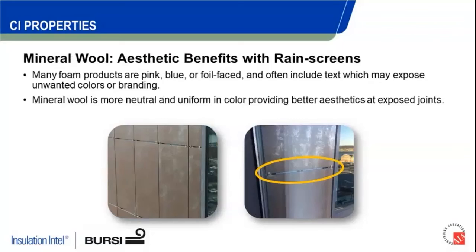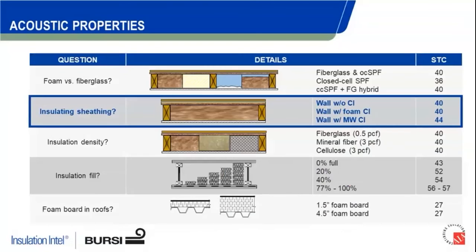Kind of almost get it in a darker, really base uniform type color that's not going to kind of telegraph through a wall system such as this. So just things to be aware of from an aesthetic standpoint. Cladding, fire performance aside, you do get a little bit better aesthetic benefit from that material if it's some type of open joint system.